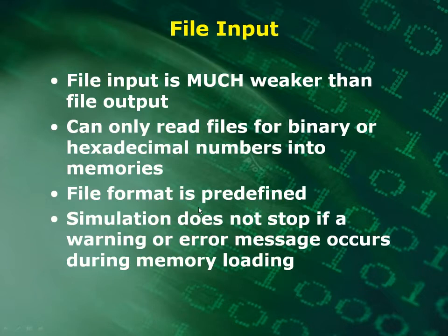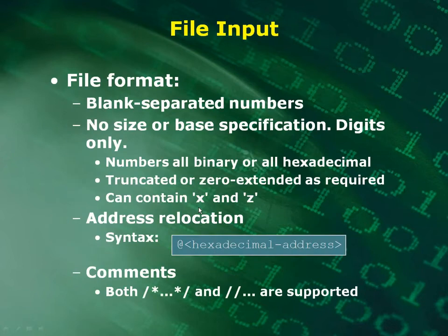However, file input is a lot weaker than file output. We can only read files of binary or hexadecimal numbers into memory, and the file format is predefined. Simulation does not stop if a warning or error message occurs during memory loading. So let's take a look at this in just a moment.